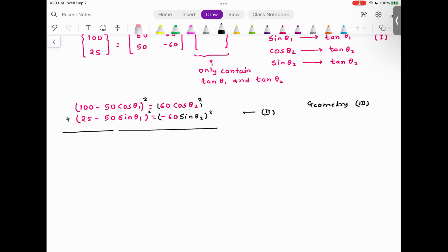So I will solve the 6 degree of freedom robot in next class. But I want you to understand that if you have a 6 degree of freedom robot, even MATLAB will not be able to give you the solution for all thetas given 6 unknown variables. So what you need to do is split it. You split the first part, which is the articulated robot, and the last 3 degrees of freedom, which is called the spherical wrist. So in today's class, I'm going to solve the first 3 joints. So let me set up the problem.